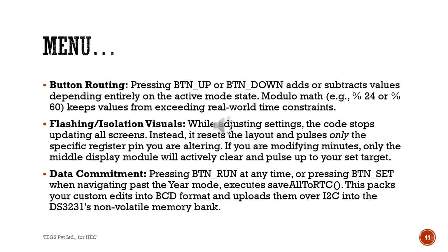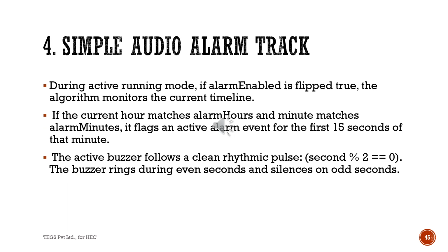Data commitment. Pressing button run at any time, or pressing button set when navigating past the year mode, executes save all to RTC. This packs your custom edits into the BCD format and uploads them over the I2C bus into the DS3231 memory bank.